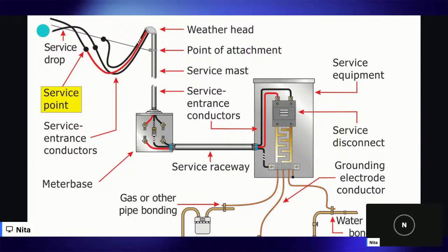Okay. So we have our service drop conductors, which are our overhead service wires that come from the transformer. These are two hot and one neutral. Each hot is carrying how many volts? 120. That's correct. Our service drop conductors, because just think the service is dropping in from the transformer, run from the overhead transformer. Now, if we have an underground service, it is called a service lateral.